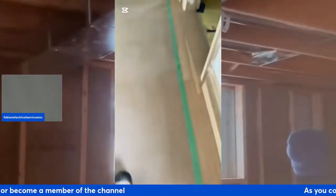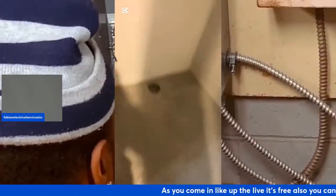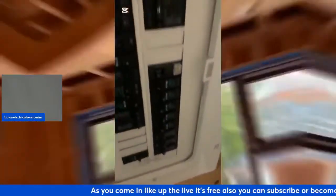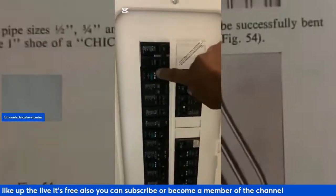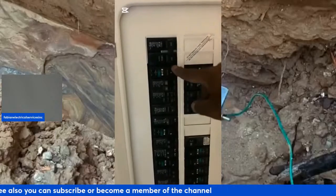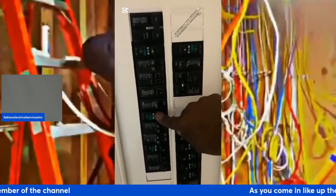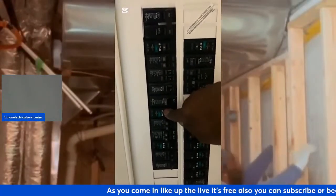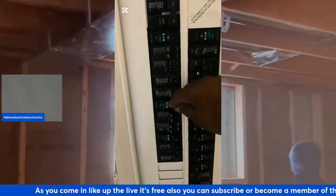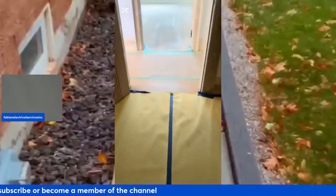Also, I just found out during an inspection that your fridge, if it's a certain distance away from the sink, calls for a GFCI receptacle, and I believe I showed it just now in the GFCI. So that was a rule that I never came across before, but I did come across it a couple of weeks ago while I was having an inspection, and you learn as you go.